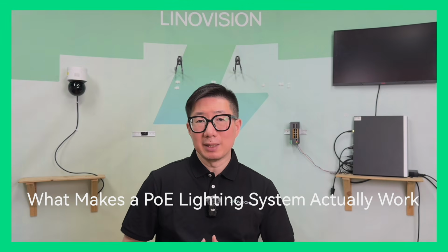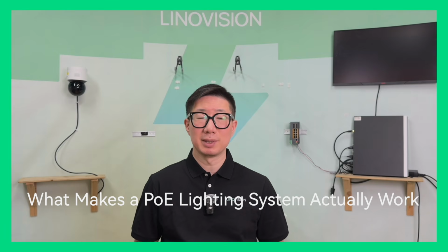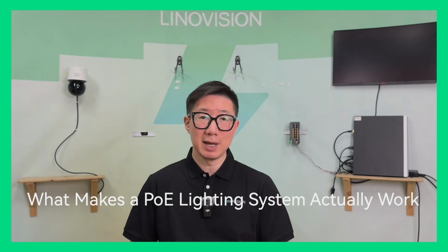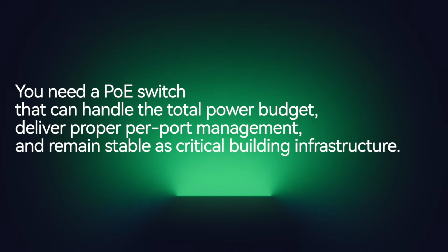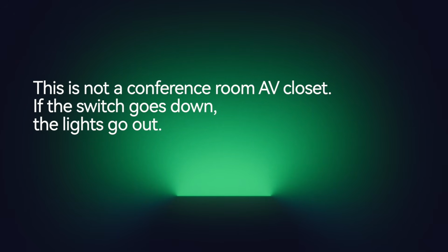Now, here's where we get into the real engineering. And this is important because saying PoE lighting doesn't automatically mean the system performs well. There are two things that have to work correctly for this to be a real lighting system and not just an interesting network experiment. First, the backbone. You need a PoE switch that can handle an aggregated power budget, provide proper port management, and stay stable as a piece of critical building infrastructure.